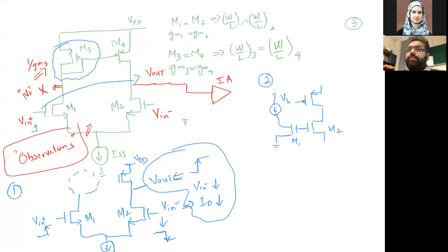If, for example, we are feeding this current I and we increase this current by some amount, delta I, what's going to happen? This is a current mirror. So this I will also increase because they are in series. So more current will flow through M1, and they are diode connected. So whatever current increase happens at M1 will also be seen on the M2 side. So here ultimately the current was increased.